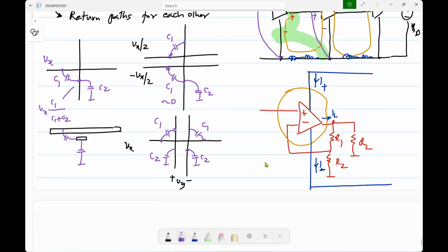Because of the parasitic capacitance between the wires and the substrate, currents will actually be going around in the substrate. But if you have differential symmetry, physically symmetric lines carrying equal and opposite voltages, it will put out less current in the substrate because the two will cancel out. So from all points of view, this fully differential approach is better.